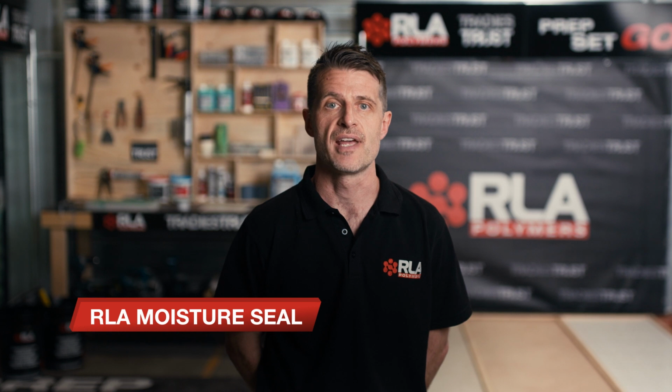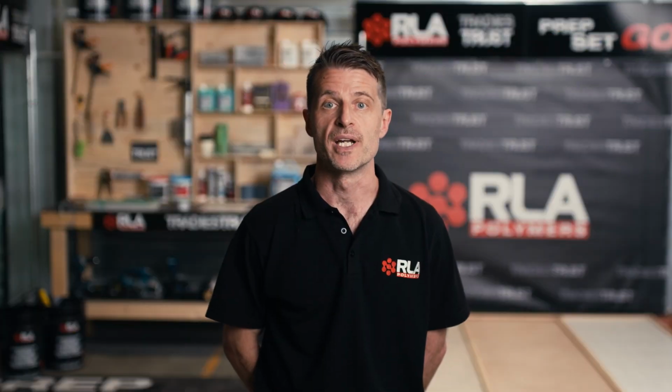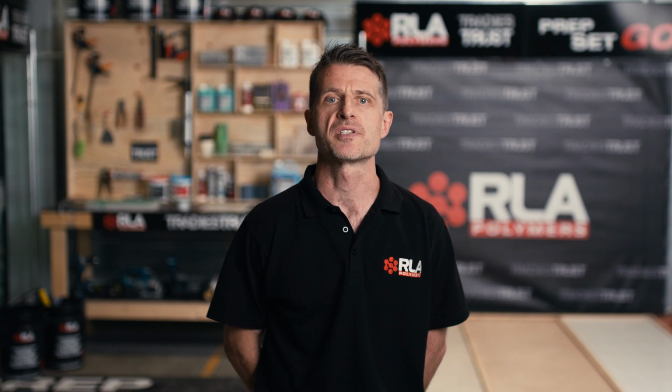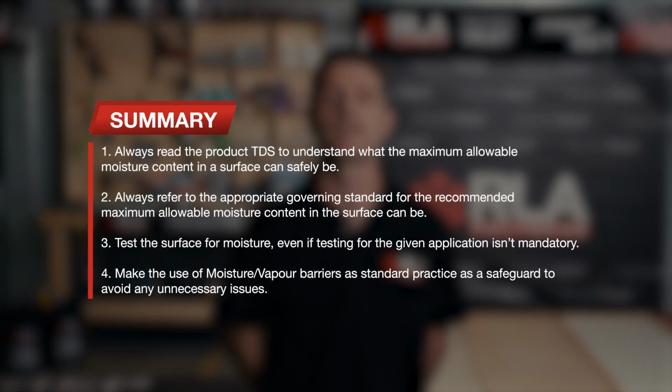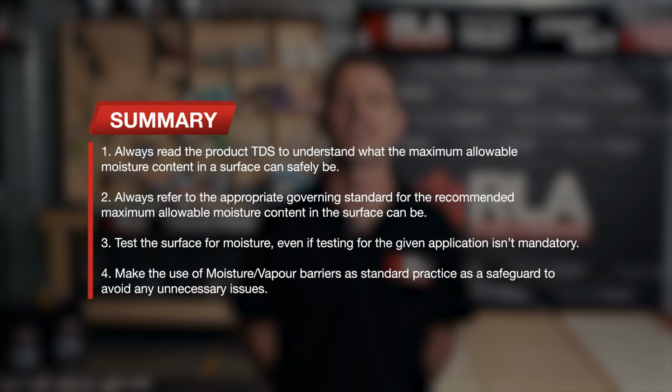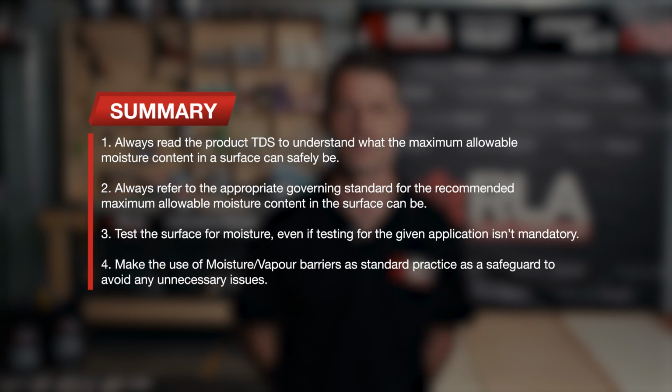So in summary, when it comes to surface moisture, there's a couple of simple things to remember before installing any coating or adhesive or finish. Number 1, always read the product TDS to understand what the maximum allowable moisture content in a surface or substrate can safely be. Number 2, always refer to the appropriate governing standard to know what the recommended maximum allowable moisture content in the surface can be. Number 3, always test the surface for moisture, even if testing for the given application isn't mandatory. And number 4, make the use of vapor and moisture barriers standard practice to safeguard against any unnecessary issues.